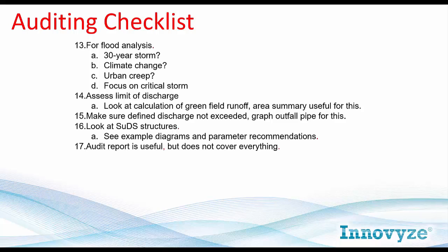Number 16 is looking at SuDS structures. And as I mentioned on the talk, things are getting more and more complicated now. We have the ability now to represent a vast variety of flow regimes, whether it's free surface in a swale, whether it's flow through gravel media, or whether it's flow through pipes, including perforated pipes, which exist at the bottom of structures.